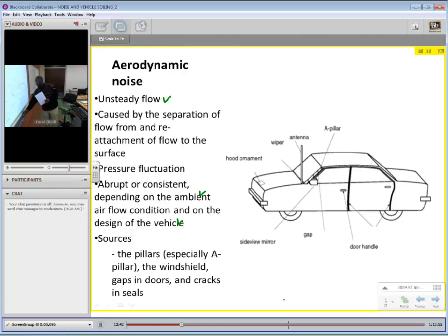If it's seals that crack under variable weather, especially for vehicles used in the northern climate, where the temperature changes from one season to the other, the seals can crack very quickly, probably even before the warranty period, and then you start to hear the noise that you weren't hearing when you just got the car.